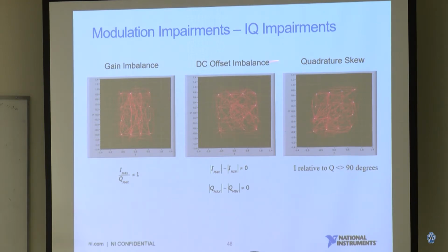Right? And when you talk about DC offset, you see here the I and Q terms, the I maximum and minimum, their variance is not the same. They don't have a consistent peak value and minimum value. So you kind of see in the constellation it's rotated. It's not a perfect rectangular box, right? They kind of rotate to this side.